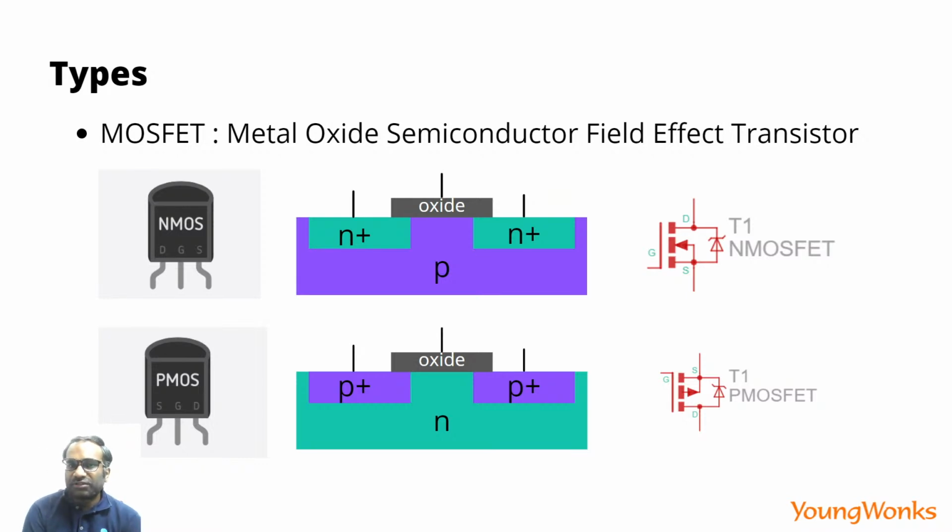Now, one thing to keep in mind is that the transistors behave differently at different voltages being applied. At a small voltage, it is as good as an open circuit. There is a section of the voltage for which it will behave linearly. Linearly meaning you increase the voltage, the current increases as well. And there is a part where it becomes saturated, where you increase the voltage further and there will be no change or very minimal change. So that is also something that would be of interest, but that's something that we can look at a later